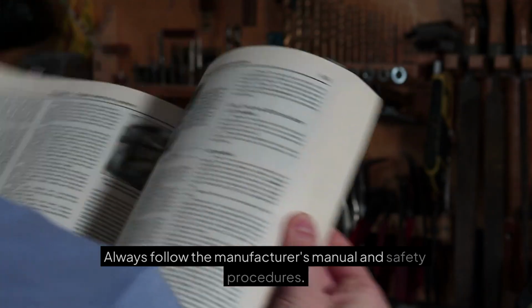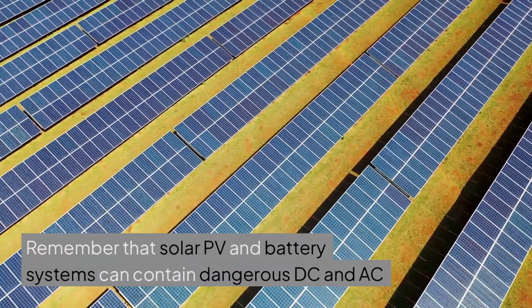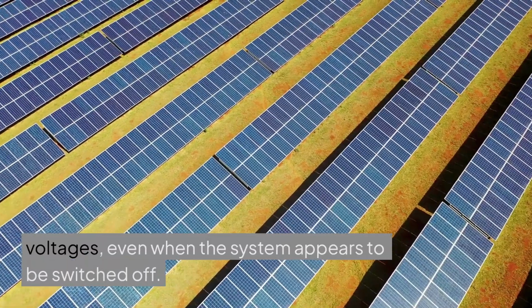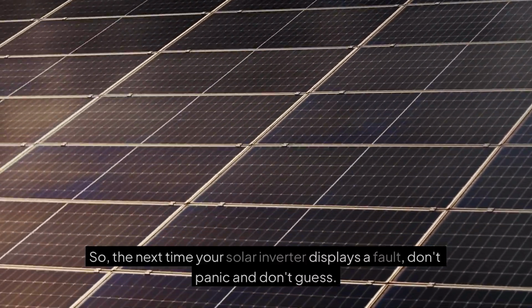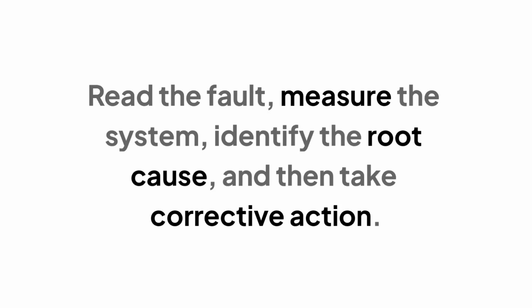Always follow the manufacturer's manual and safety procedures. Remember that solar PV and battery systems can contain dangerous DC and AC voltages, even when the system appears to be switched off. So, the next time your solar inverter displays a fault, don't panic and don't guess. Read the fault, measure the system, identify the root cause, and then take corrective action.